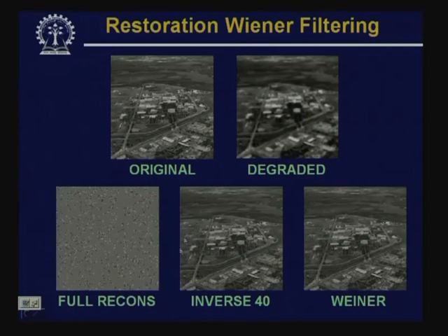for best appearance. Now, if you compare the inverse filtered image with distance equal to 40 with the Wiener filtered image, you will find that the reconstructed images are more or less the same, but if you look very closely, the Wiener filtered image is slightly better than the inverse filtered image. However, visually they appear to be almost the same. The advantage of the Wiener filter is that I do not have to decide what extent of frequency components I have to consider for restoration of the undegraded image.